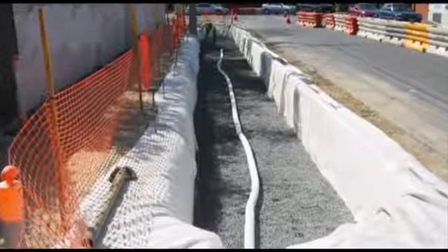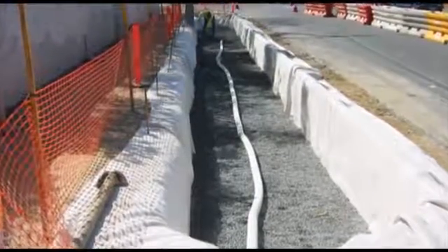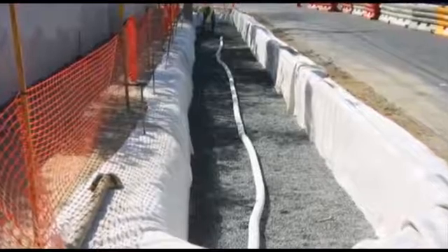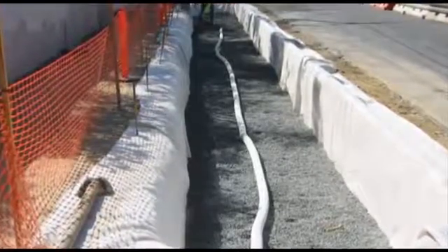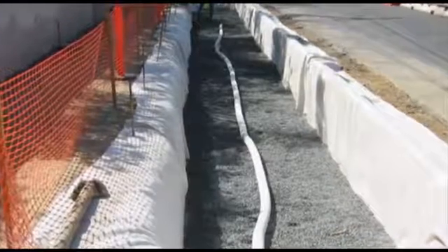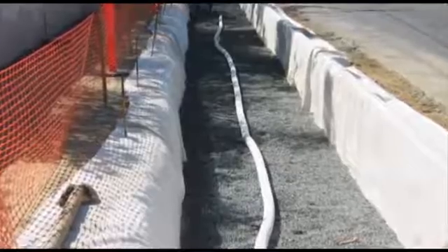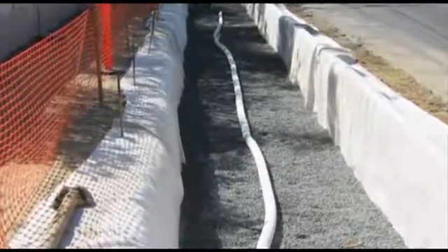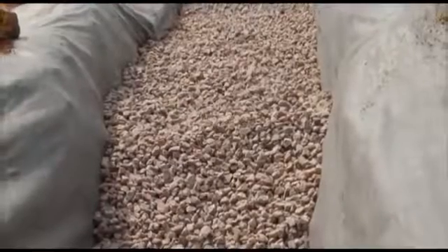The most simple example is a French drain, where the geotextile is placed around the trench to prevent the surrounding soil from entering the trench and clogging the drain. These types of drains are typically used adjacent to roads and require the pipe in the middle to collect any water entering the system, such as runoff from the road surface.